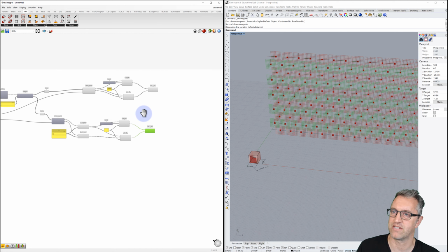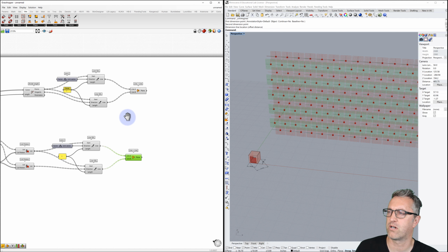So hopefully that makes sense. There's limitations in terms of how you define planes. And in this case, because we had that point, because the divide function comes with the tangents, it's easy for us to get those two lines as a way to then define the plane. So now that we have the plane, let's map our boxes to that.